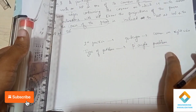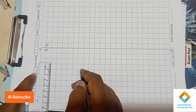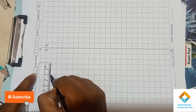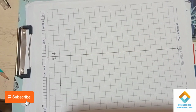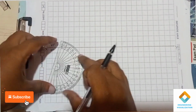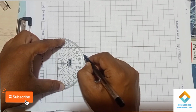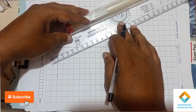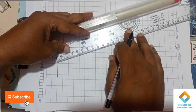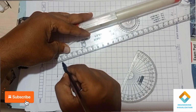And now we have to construct a pentagon with respect to the corner position, of dimension 25. Using the scale, draw a line of length 2.5 centimeter, that is 25 mm. Then use the protractor for marking an angle of 72 degree. The outer angle we have to consider here, remember it, 72 degree exactly we have to mark. Now passing through that angle point from the reference end, we have to draw a line of length 25 mm, that is 2.5 centimeter, from the scale.